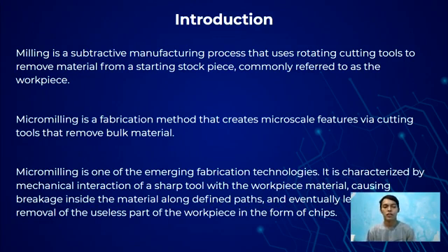And micromilling is one of the emerging fabrication technologies. It's characterized by the mechanical interaction of a sharp tool with the workpiece material, causing fracture inside the material along a defined path and eventually leading to removal of the useless part of the workpiece in the form of chips.